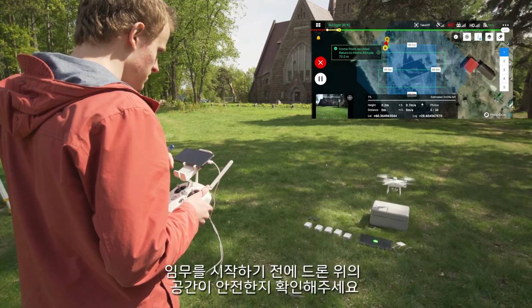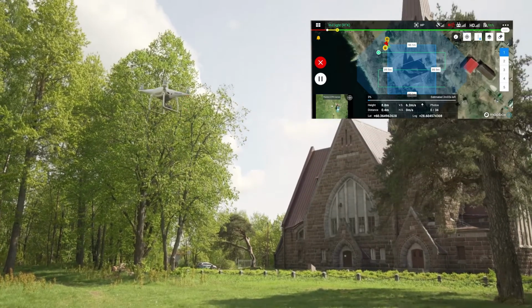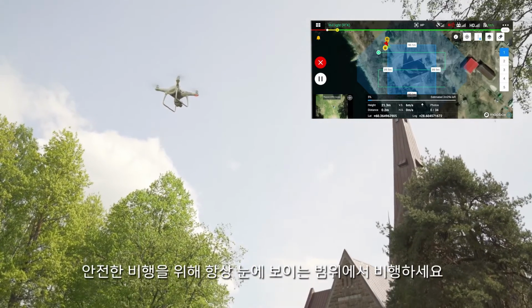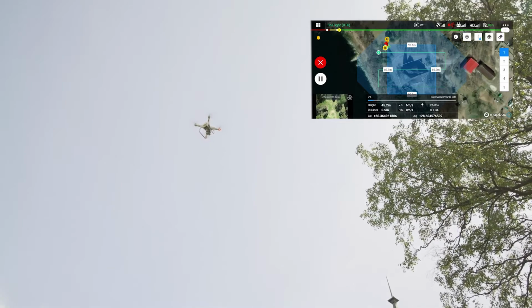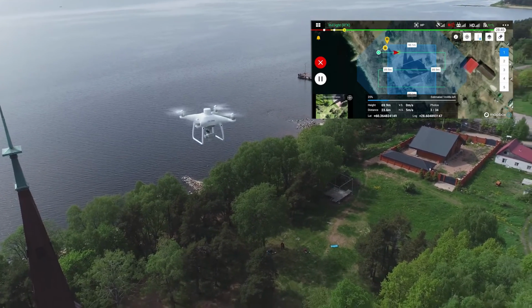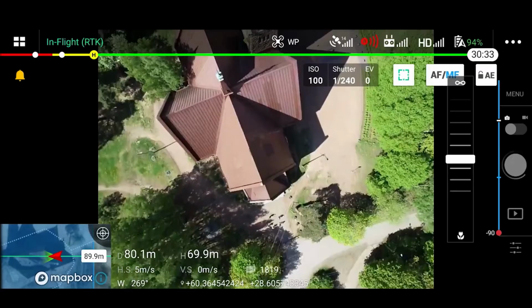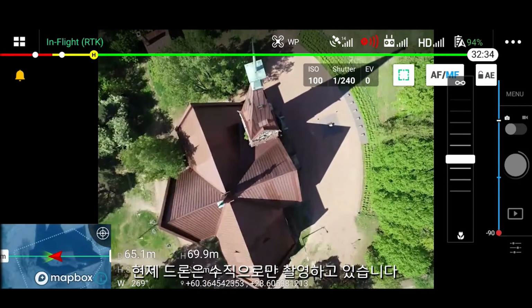Before starting the mission, make sure that the space above the drone is free. Always keep direct eye contact with the drone to ensure safe flight. The drone is performing the nadir flight, taking only vertical photos.